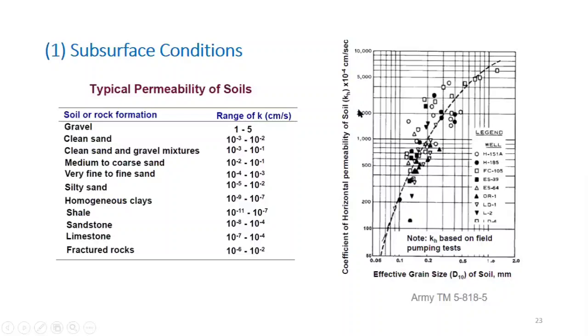Of course, it's an empirical relationship, so you may verify it through some kind of model or lab tests as well. If you explore the literature, you will find a lot of lab test methods to calculate the vertical as well as the horizontal permeability of the soil, which you call anisotropy with respect to permeability. So you can explore that.